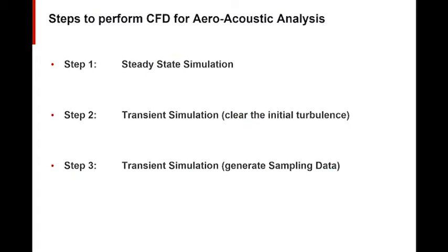So we launch our software through the Kicker, and we launch our preprocessor. We have different modules, and once we open the preprocessor, we can open our model file, which is the native format for our SC-Tetra. And typically, the first step we do is we define the regions, but for this demo, we prepare the model. So I'm just showing where the inlet is and where the outlet and where the wall regions are. And pretty much the entire surface of the muffler is a wall here.